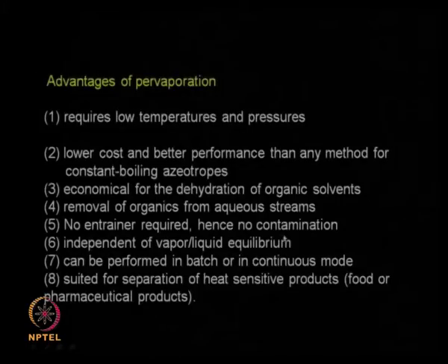Okay. So distillation, separation of two or three or multi-component liquids, happens because of this vapor liquid equilibrium. A liquid which has a low boiling point will have more vapor present in the gas phase, a liquid which has a higher boiling point will have less vapor present in the gas phase. So because of this, you are able to separate out the low boiling component in the vapor phase and the high boiling component in the liquid phase. That is what is called vapor liquid equilibrium.